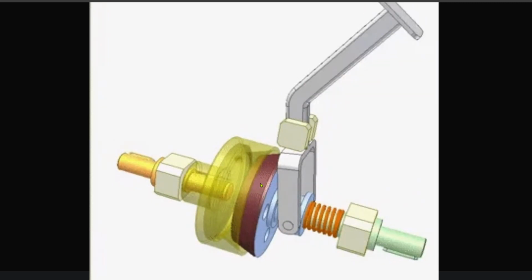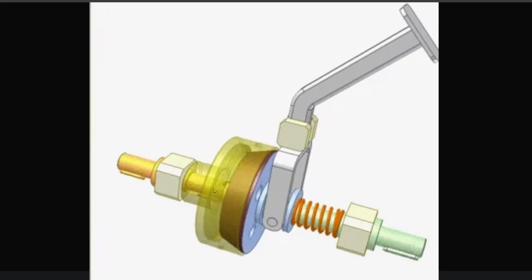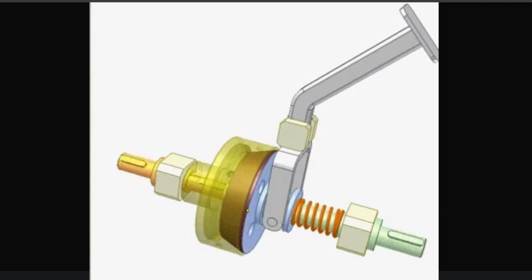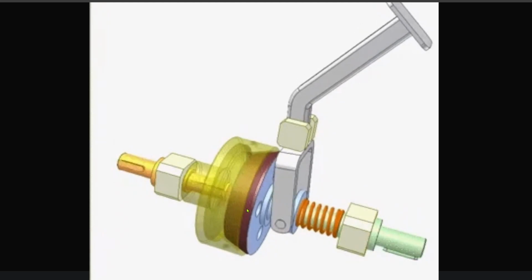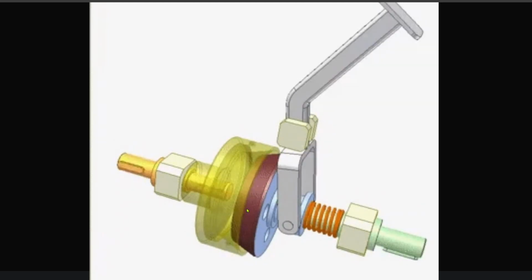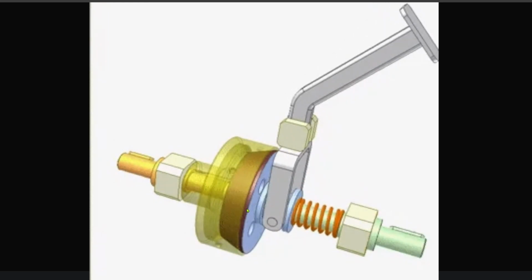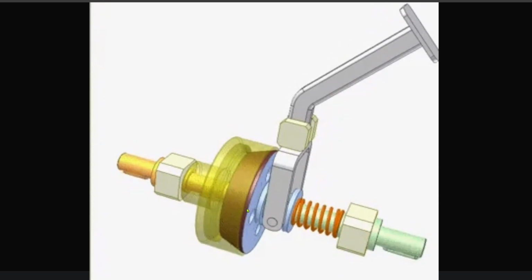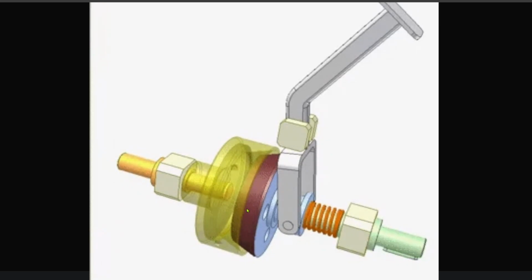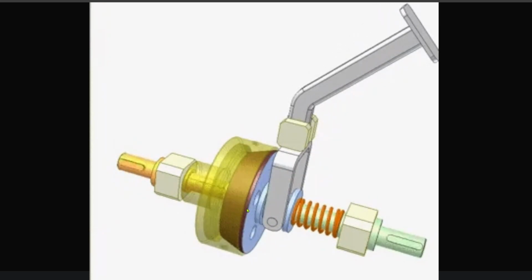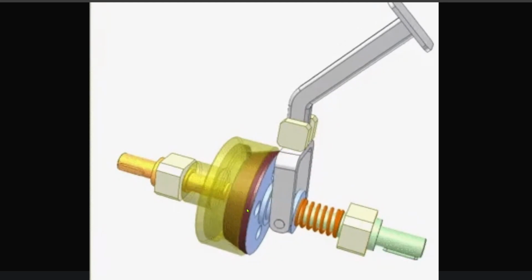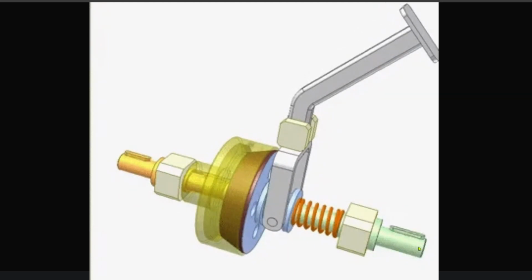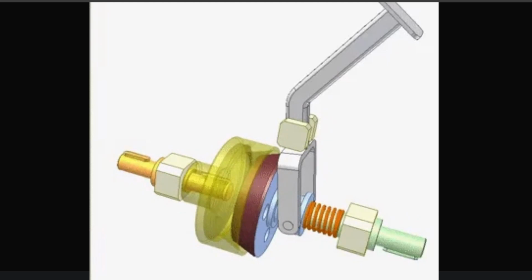As you let the foot off of the pedal, this conical disc will push into this other disc here. You'll notice it's red here. That is usually some sort of abrasive material, so think sandpaper. And so you imagine if you have your hand and you're waving your left hand back and forth, and then you go and you barely put your right hand on it, but you keep moving your left hand, it's going to slip past. That's what happens in a clutch. That's your friction zone, and you get slipping. Now, if you push your hands together, as you move your left, it's going to move your right. The friction is causing it to move, in this case, whatever we're turning in the back. The output shaft, which could be going to a propeller, or in this case, we're going to build a car, so it would be the wheels. And so that's what a clutch is.